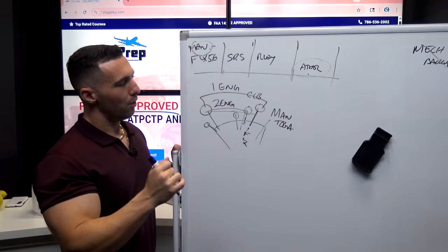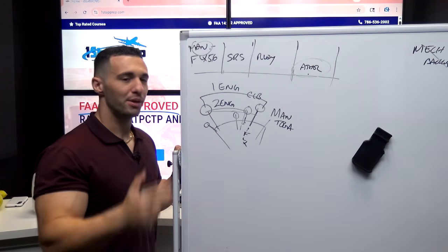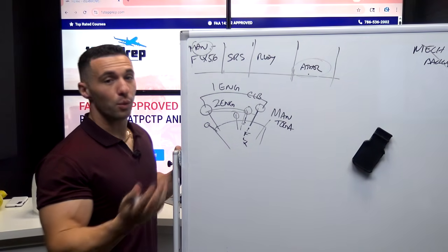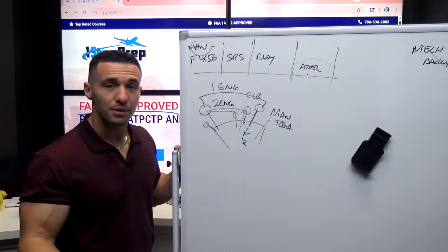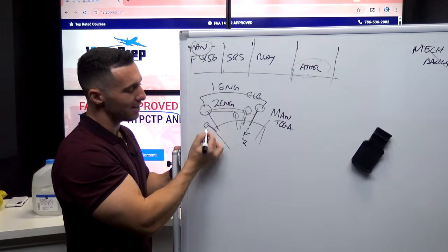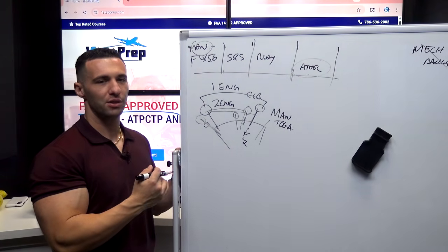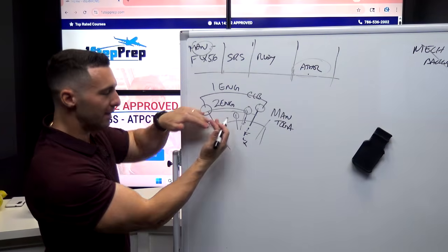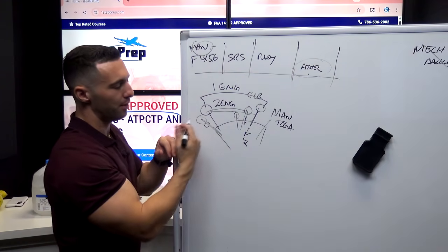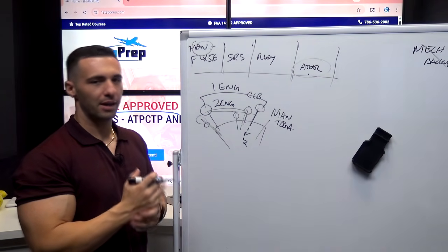So, when I said earlier that alpha floor is a predictive function of auto thrust, one of the ways I can turn it off is by deselecting it, but I can also bring the thrust levers back to idle. Well, why does that work? Because you're out of the active range. The moment you bring it out of the active range back to idle, not on the TOGA, it will indeed disconnect alpha floor and get rid of TOGA lock.